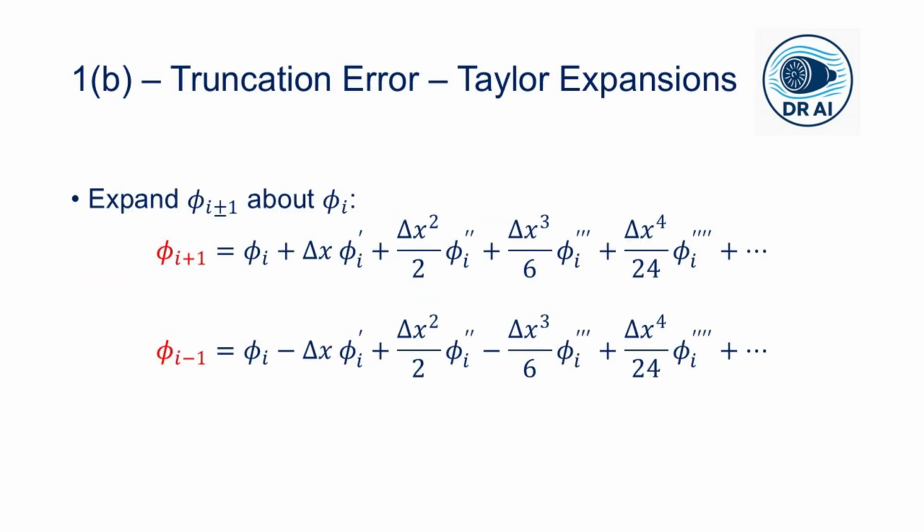Now, moving on to find the truncation error and the order of accuracy, we go back to calculus. We assume that phi is a smooth function that satisfies the exact partial differential equation. Then we insert that exact phi into the finite difference formulas and see what remains. This remainder is the truncation error. It tells us how much the discretization deviates from the original equation.